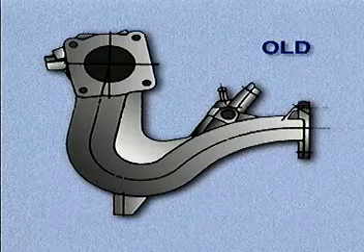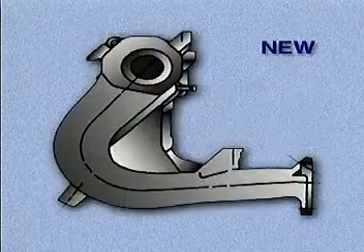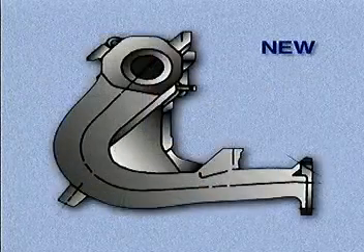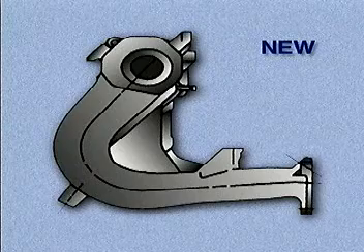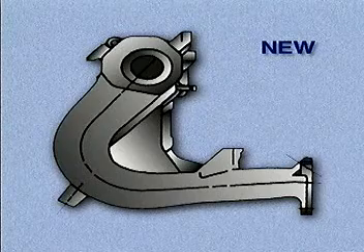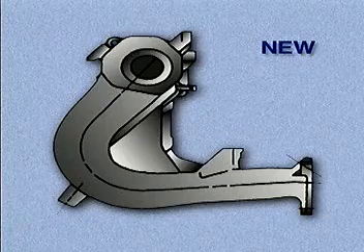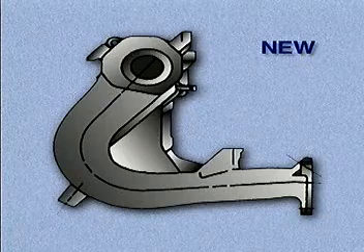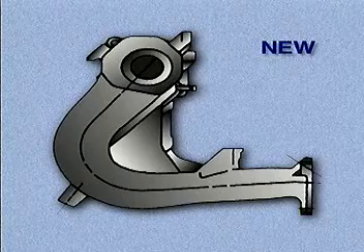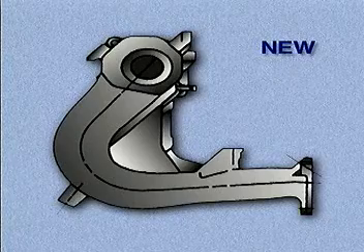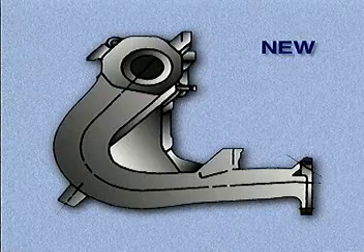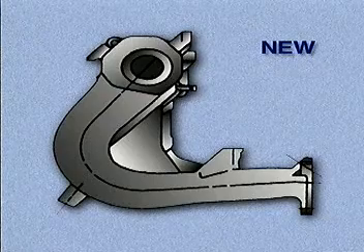The intake manifolds on both engines have been redesigned to increase engine breathing capacity by reducing the resistance to airflow through the manifolds. This was accomplished by using a straight port design. In addition, the general wall thickness of the 1.5 liter intake manifold was reduced from 3 millimeters to 2 millimeters, resulting in a weight loss of 30% over the previous design.